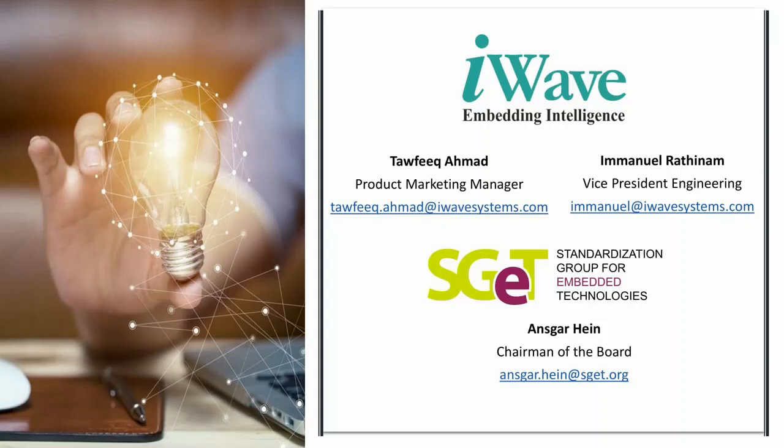So does the power button affect the PMIC on the SOM? No, it does not actually. So it's how we implement, correct? You need to have a power button on the carrier board. It depends upon which PMIC and which processor you use. But in general, in the design, it's taken care of. It does not affect.